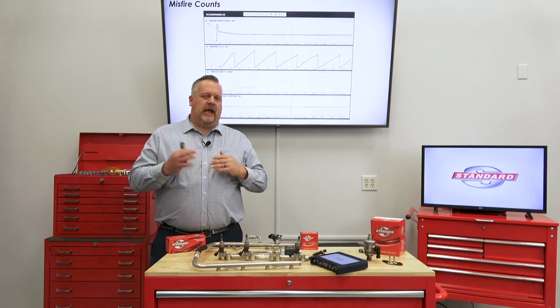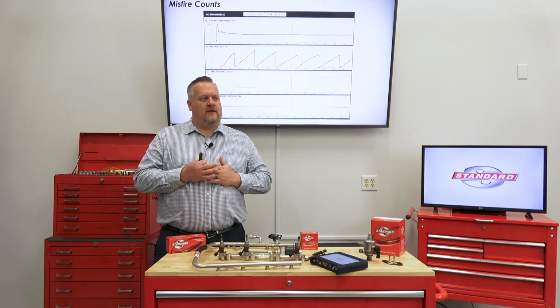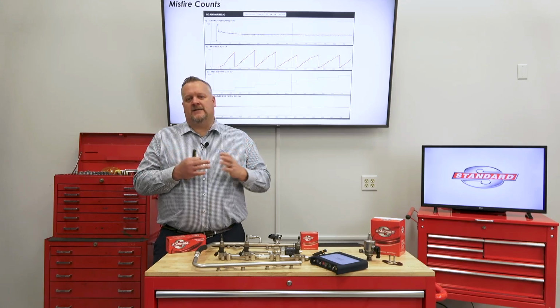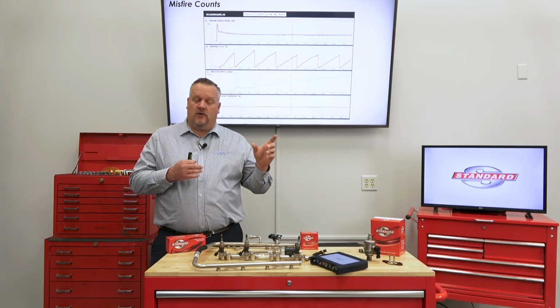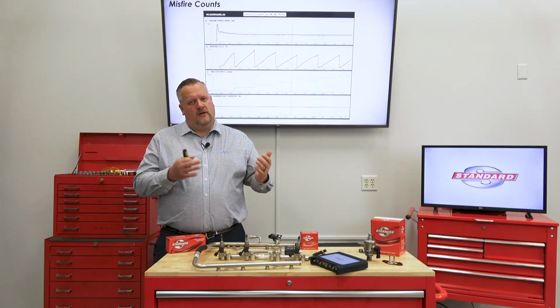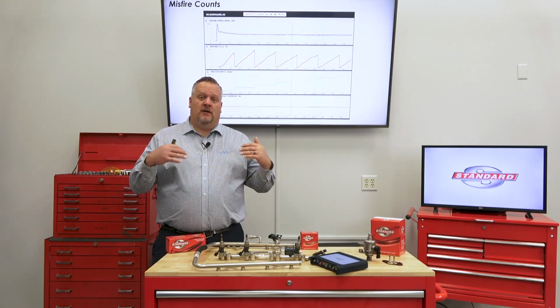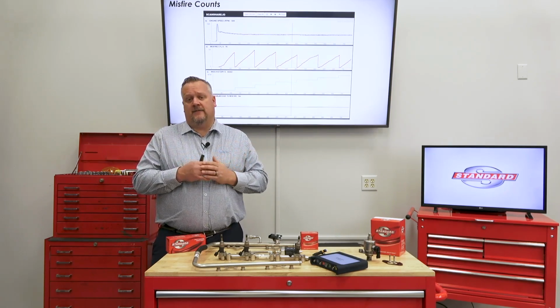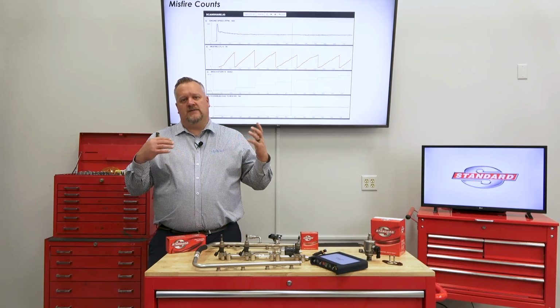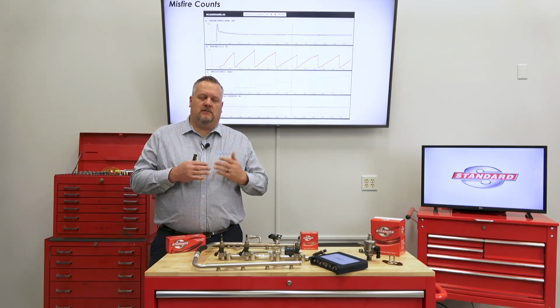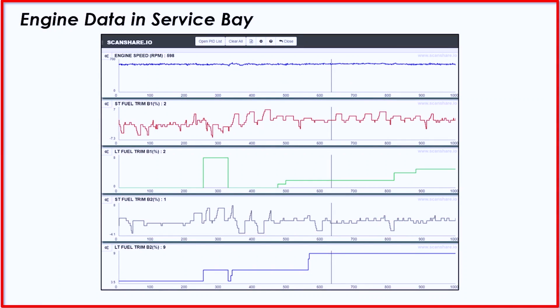Now, I know the questions are going to start coming in here of like, well, if it's an injector issue, wouldn't it get worse under load? Depends. Sometimes the wider the pulse width on these things, we're going to deliver just enough fuel, or if it's a drippy injector, we're going to scavenge. Remember, this is not a GDI vehicle. This is a port style. And so there might be some scavenging effect throughout the intake there to fuel this cylinder off idle.